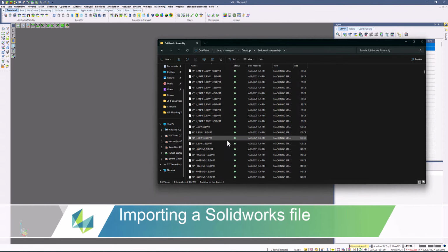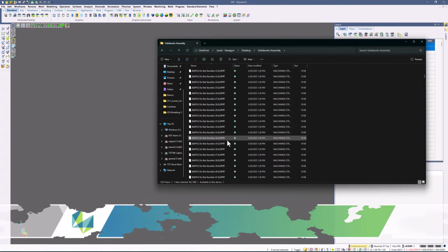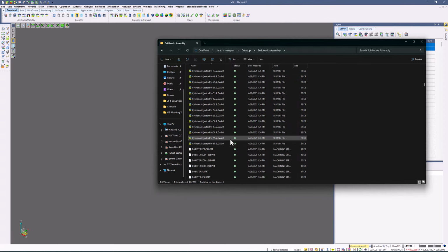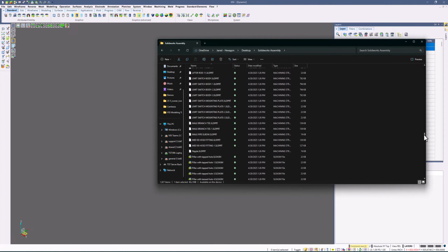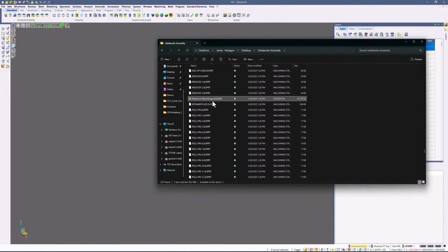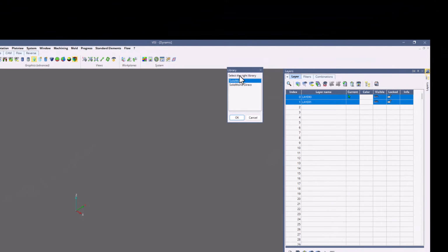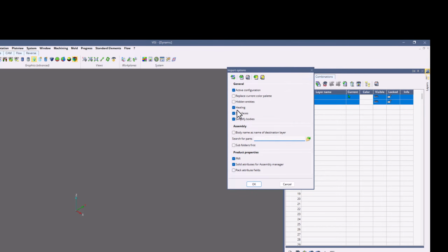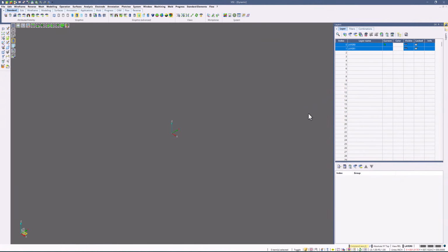In our example, we received a group of SolidWorks files from a customer. You see several solid part files, drawing files, and assembly files, all of which are supported within the Visi imports. When opening up the master file, it will recognize all of the associated parts. You will then receive import options which allow you to change settings of how you will import this file. These settings include healing, sewing, PMI data, and many more different import options. You can choose which ones are selected and which ones are not automatically.